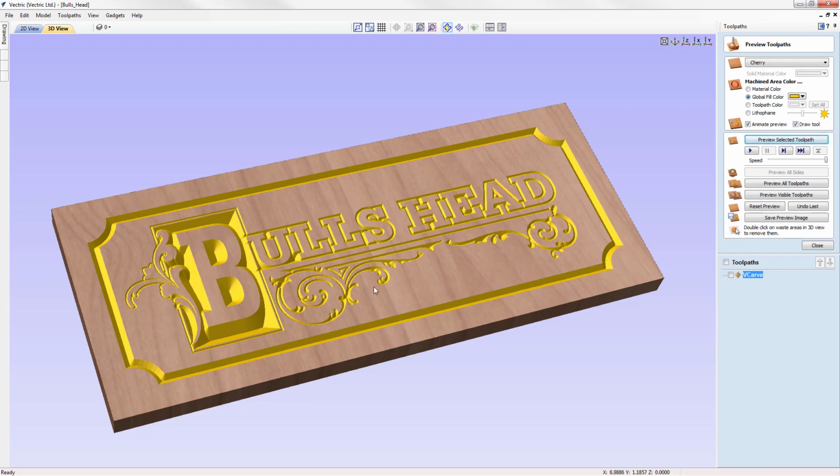Okay, so I'm happy with this design that we've got here. It's very important that your part looks correct at this stage. As you've seen, we've made several iterations to this part, previewing those changes until we like the look of the preview. The toolpath preview shows you an accurate representation of what we'd see on our CNC machine if you were to go ahead and run these toolpaths.